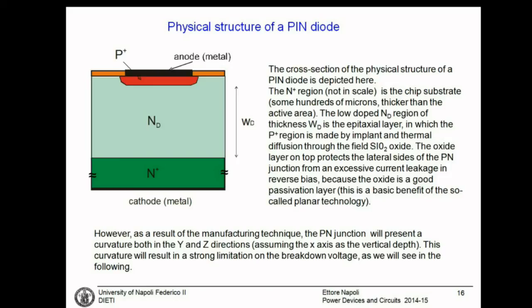On top of this, there will be oxide, defining the masks, and you can also diffuse or implement the anode metallization. The structure is very, very simple. This is a cheap technology, much simpler than digital electronics where you need 20 masks, many layers of metallization,